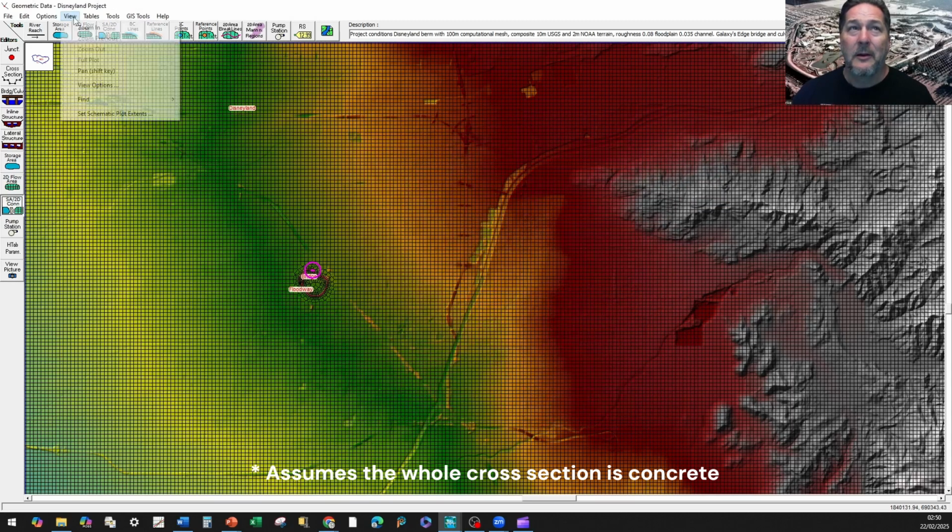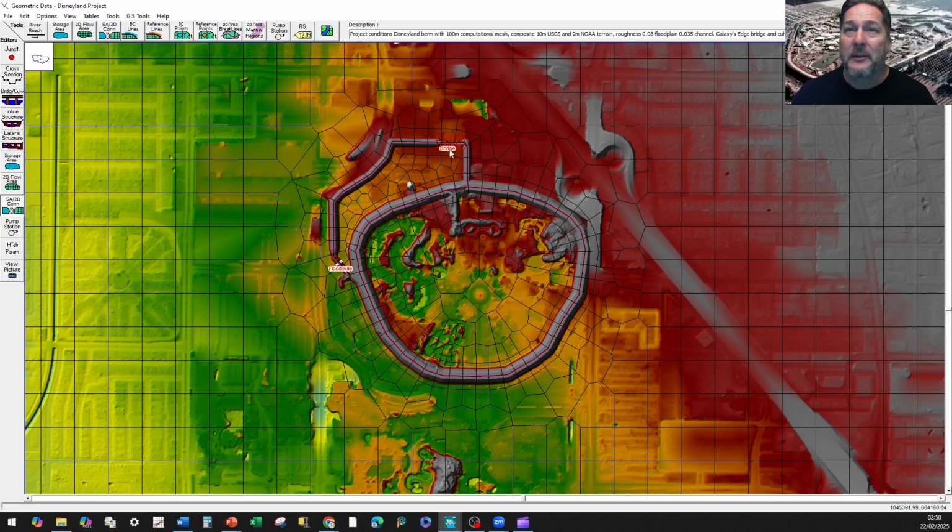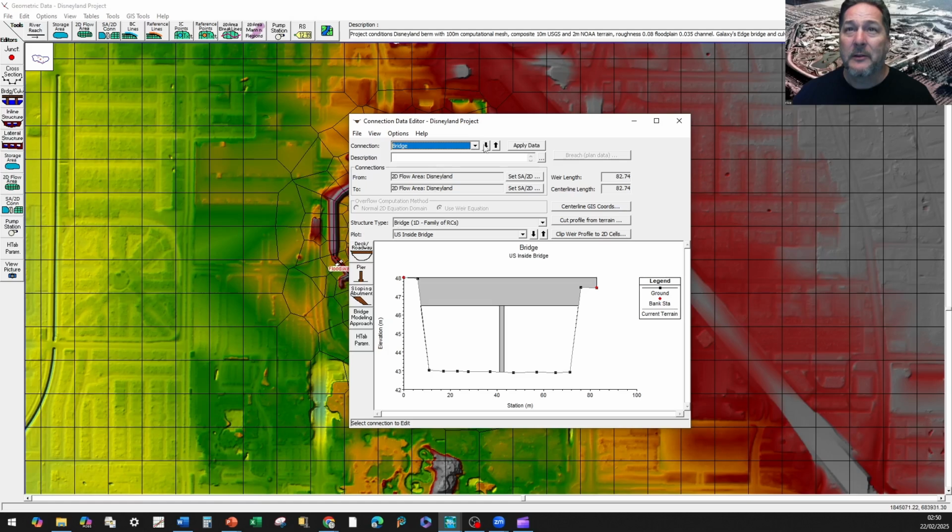So that way, I'll go ahead and zoom in on this so you can see what's going to happen here. We'll be able to let some water in through this bridge here. Maybe for this one here, also on this connection, let's do something simple to prevent any of the flow from coming up into it this way. So flow can go in this way, and if we want to keep it one way, then we can just go ahead and edit this culvert here.